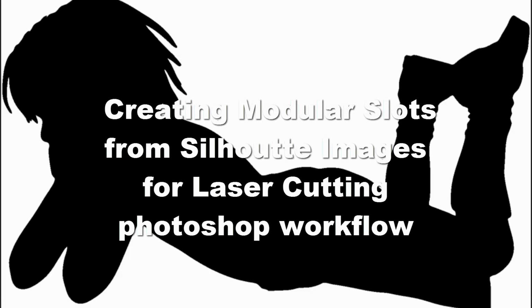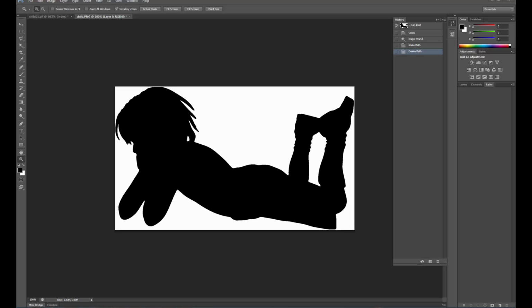Okay, we're going to start out the tutorial on how to make notch swatches from silhouettes by showing how to take a black and white, silhouetted image and convert that into a path that can be imported into Rhino. So basically we're going to go from this black and white image, create a path from the image, export that path to Illustrator and then load it into Rhino as a .ai file.